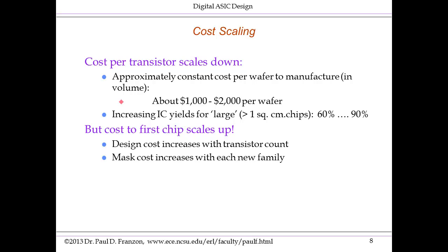When you introduce a new generation, the yield is low, and fairly quickly the yields are in the 90% range, even for relatively large chips. So in high volumes, the cost per chip has stayed, actually improved slightly due to increasing wafer size over time. Though you can argue, depending on the details of the costing, it's stayed roughly the same, maybe improved a little bit.